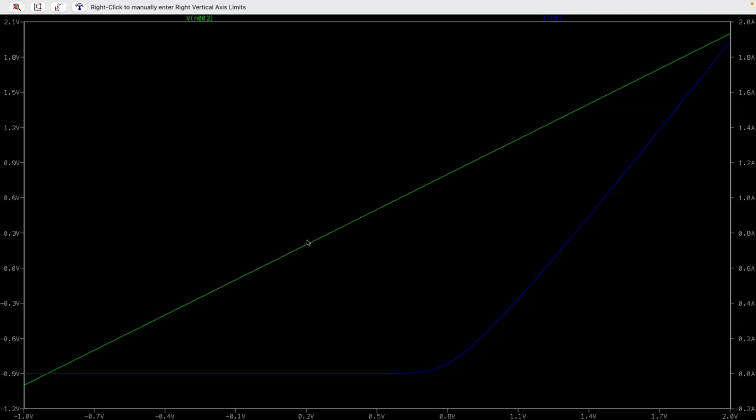If you're doing switching, you almost always want it not in the linear region because you're going to be losing a lot of power in the device, which means it gets hot and your efficiency goes down. You have to make your device larger, more expensive. Nobody likes that.